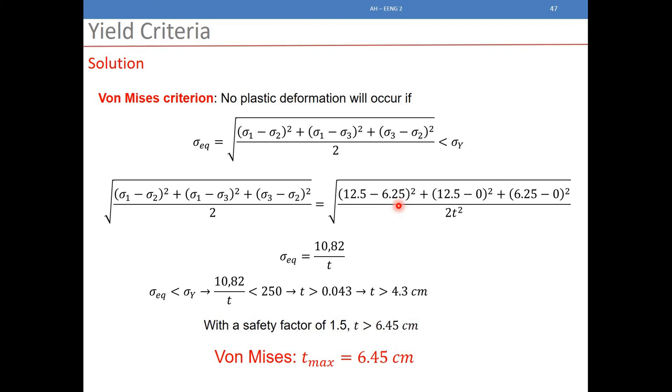Now everything that we learned in this lecture about the first chapter, the plane stress, the circle of Mohr and the yielding criteria, we'll do some problems on them together in tutorial number 6. So we can do a revision, and also draw a Mohr circle and check how we can use it. For now, we do a revision of Tresca and Von Mises because these are the criteria that are used in engineering, and we also use the same equations here. As you can see, it's very simple. Just calculate the principal stresses and directly compare to sigma y.